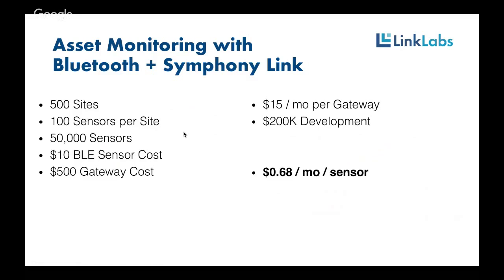And it's a combination of using the lowest cost hardware out there, which is Bluetooth, and doing this one-to-many architecture where your expensive cellular connectivity is at a gateway where you're backhauling 100 sensors at a time through it. So this is an architecture that we always recommend to customers if they have a fixed site with a lot of sensors. It's when you have only a few sensors that need to go anywhere that we push people toward LTE-M, because the headache of not having to manage the network infrastructure goes away.